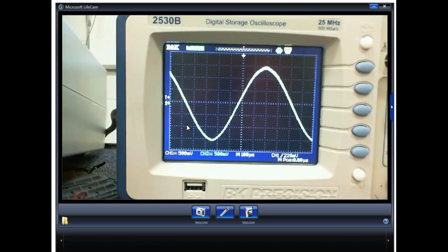I might have to get a bigger pot. Why? I got a 10K pot. And what's the problem? We'll try it. We calculate our input impedance to be 13.2K. So if it's 13.2K, I won't be able to do it with a 10K pot. But I can get a resistor, right? And put it in series. But we'll see if we can get it.